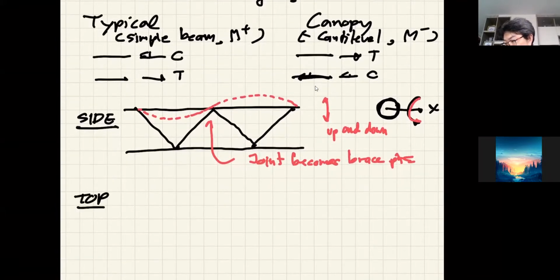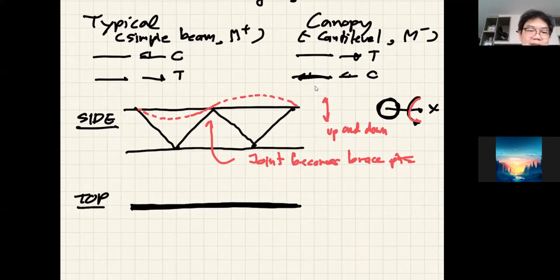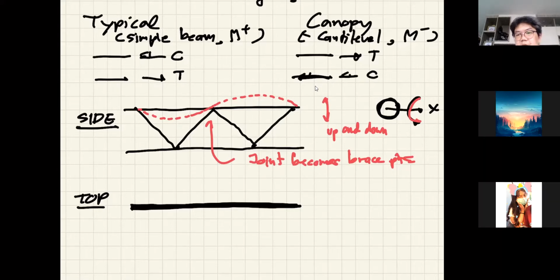I will see just the line, right? I can no longer see the diagonal members or the vertical webs if I have any. So let me try to thicken it. From the top view, I can only see this. Are you guys with me? Yes. Okay, so if I use the same picture of the cross section here, the buckling will now occur about the vertical axis.